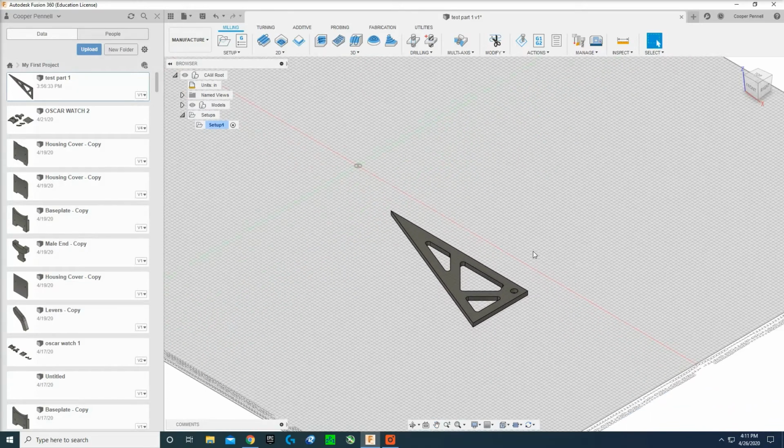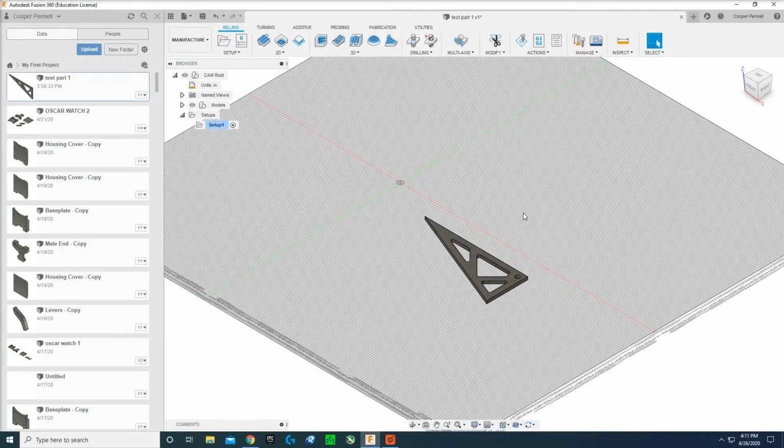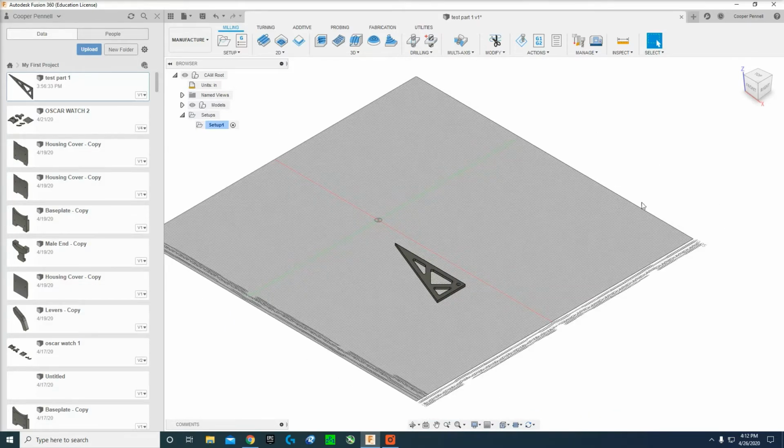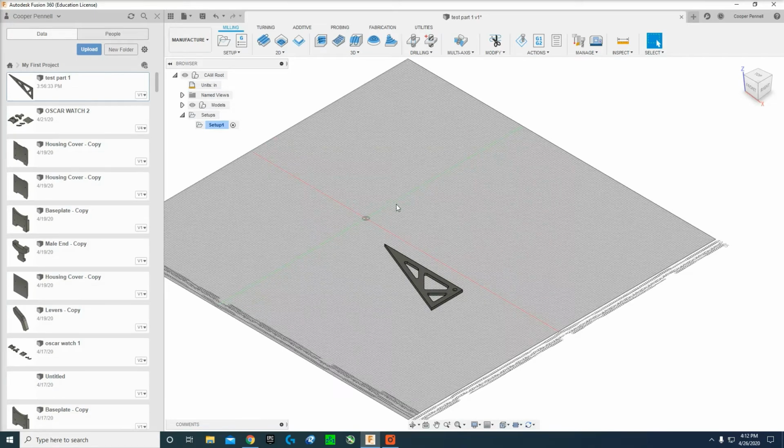So you need to do one of two things. Either space out your parts further than right next to each other, or cut out one part at a time. So maybe you cut out this piece right here, and then if you want to cut out a piece right next to it, you change your four screw locations to be closer to the part, cut out that part, and move along, going systematically slower and more methodical.